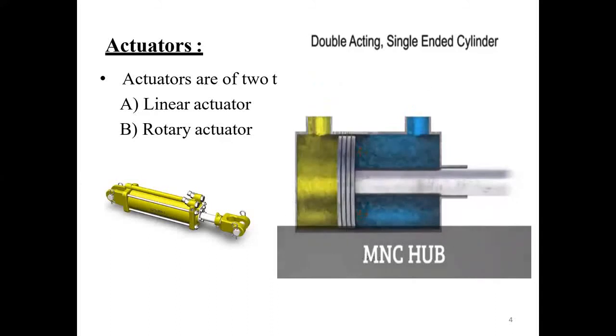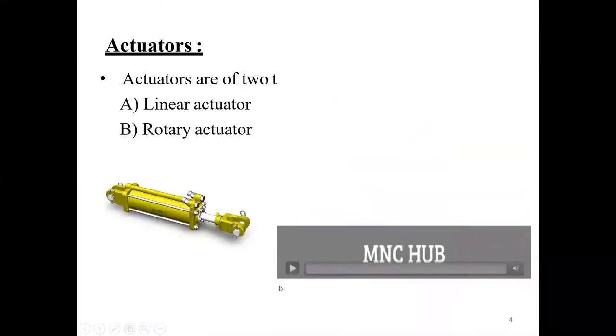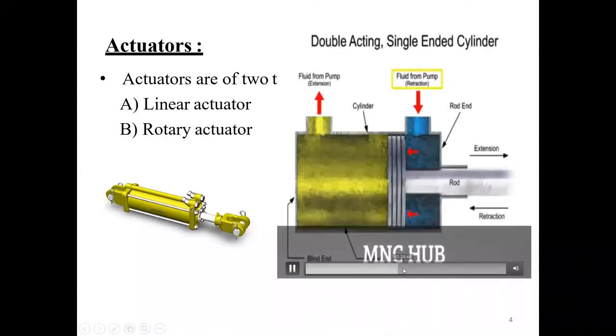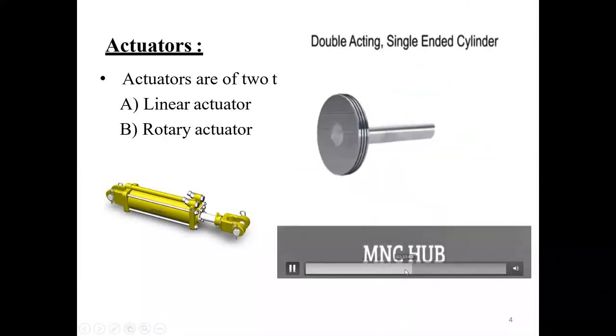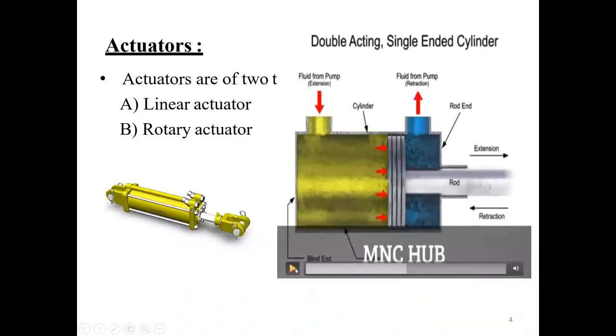We are achieving both the strokes, extension and retraction, by the pressure of oil in the double acting cylinder, and in the single acting cylinder we are achieving the retraction stroke by spring action.